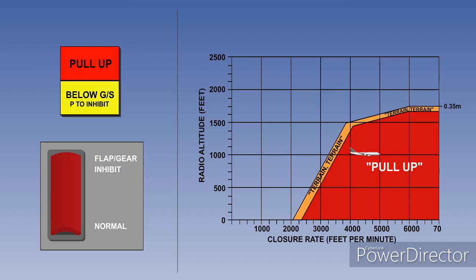After leaving the pull-up area, the audible alert will again be heard while in the terrain segment. "Terrain! Terrain!" If both boundaries are penetrated in the landing configuration, then only the repeating audible alert message is heard. This is repeated every second and a half.